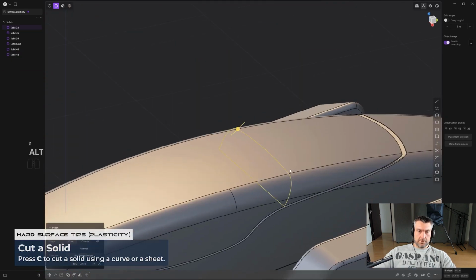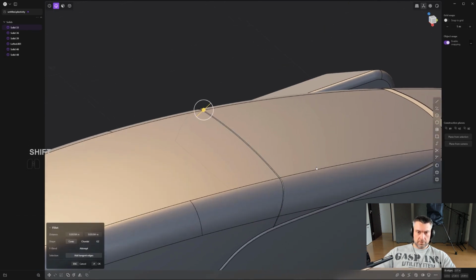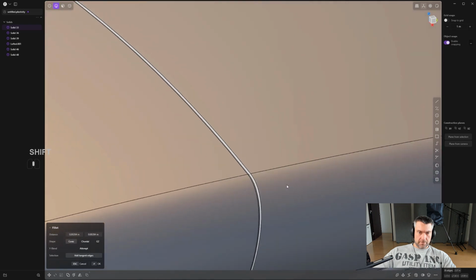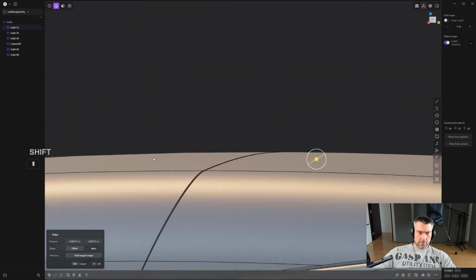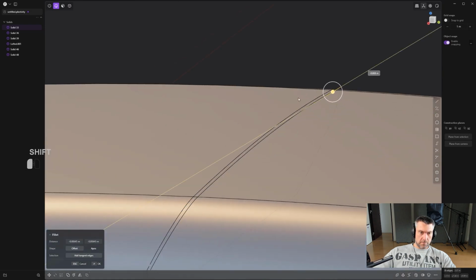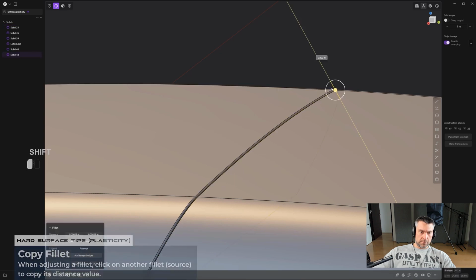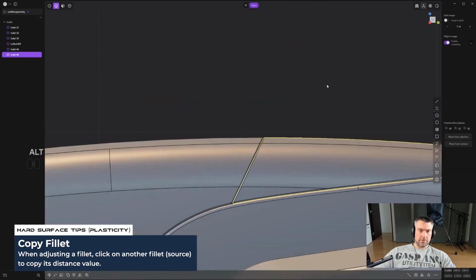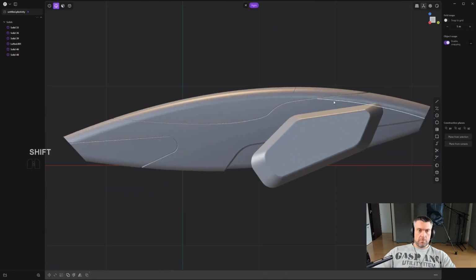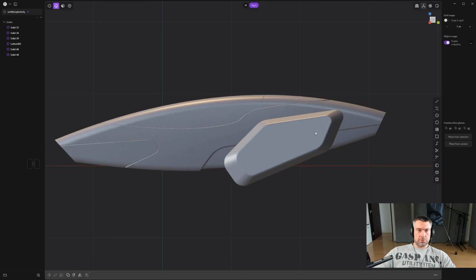We're going to bevel them separately, okay? So bevel this one. These bevels have to be tiny, okay? Tiny, don't overdo it. And make sure it's a bevel, not a chamfer. This is a chamfer, I think. You see that? Oh, wait. This is a bevel, right? Okay, one bevel. And then this one. Start beveling and just simply click on that and you're good to go. Right click and you're good. It's going to be quite helpful for texturing, and it's also going to separate this whole ship silhouette a little bit.